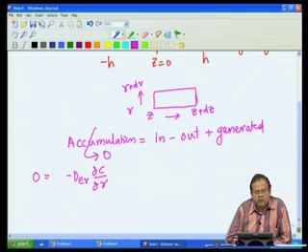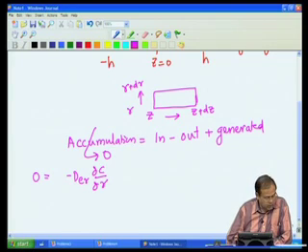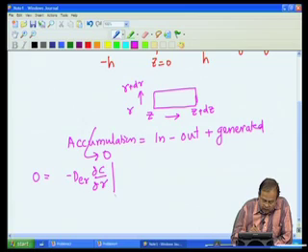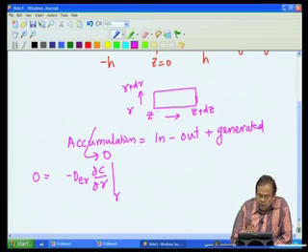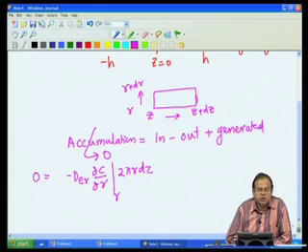Let us call it minus D_r at r. So, this is flux, so it has to be multiplied by the appropriate area, and what is that area? This length is dz. So, that area is the surface area 2 pi r dz. This is what is coming in at r.